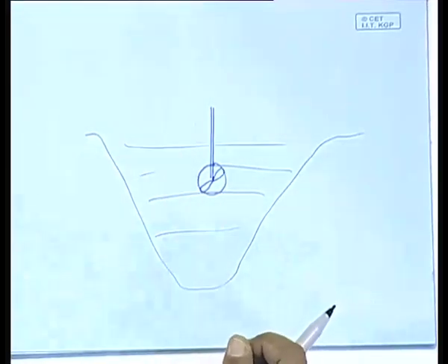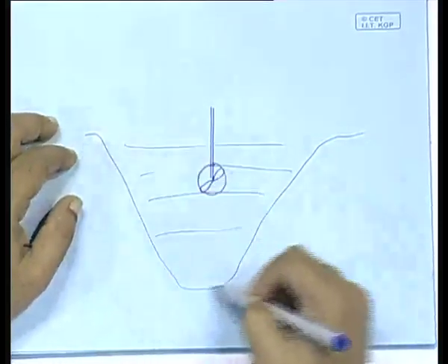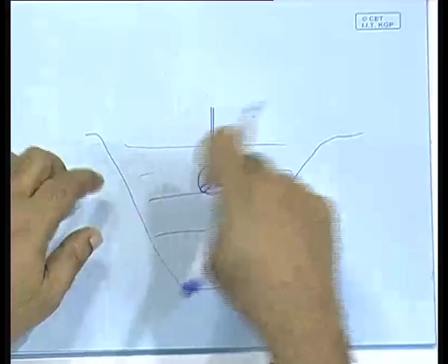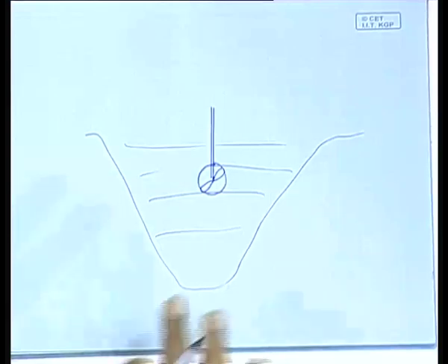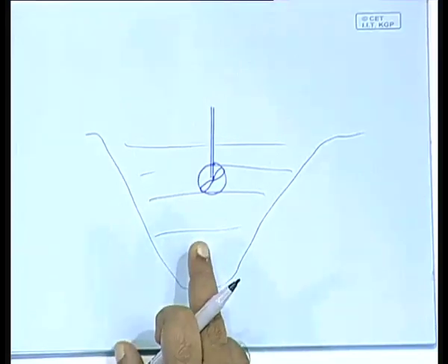So then you make a graph paper, make this contour, and at every point there will be a different velocity, and then you can make an average. Clear? This is obviously a more accurate method. But obviously this will not be applicable to cases where there is turbulence in the stream itself. The turbulence will occur, for example, where there are bends. Even in relatively smoother rivers there are bends, and in the bends you should not do this. But for the rivers in the rocky regions, obviously this will not be applicable. So you need some other method for that.